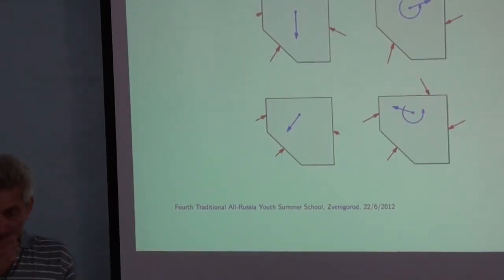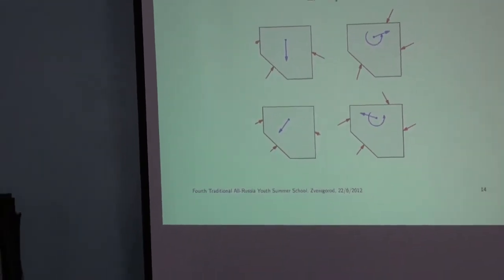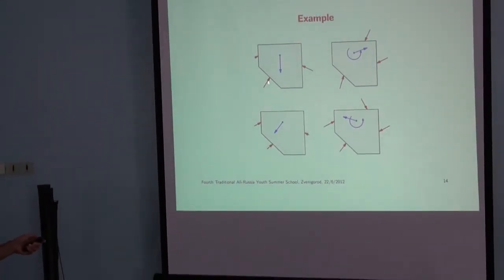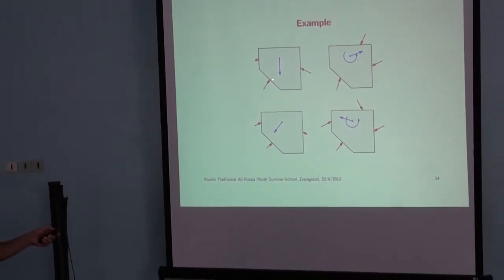So here's an example, just to see it does something. The contact points are here, here, here, and here, and this is just the dead weight of the mass. That's the CG, and that's the weight. And so, not surprisingly, you don't push from the top if you're holding it up against gravity, but you apply these forces here. And notice that this one is right on the friction boundary, and so is this one, and this one is not on the friction boundary.